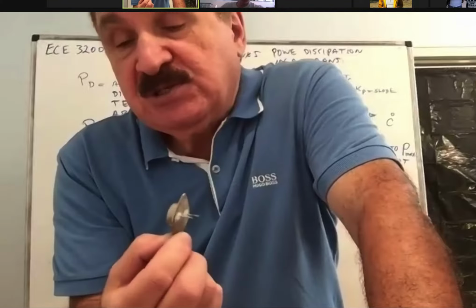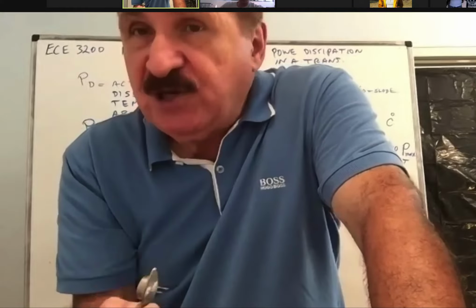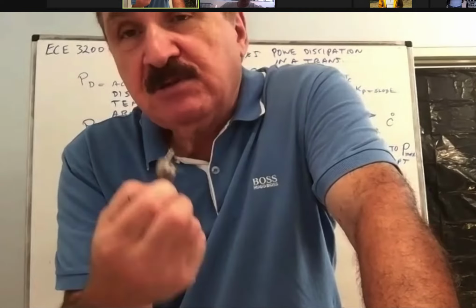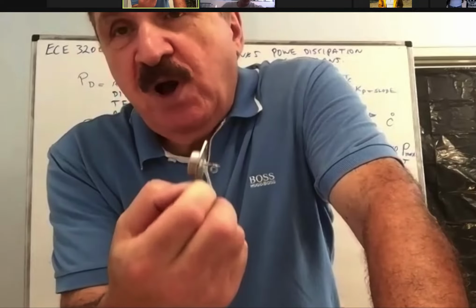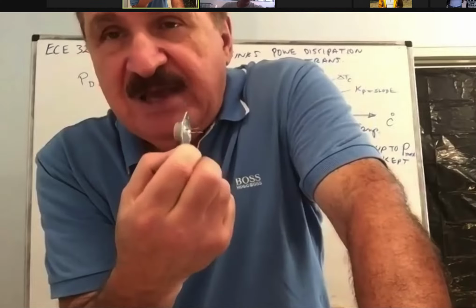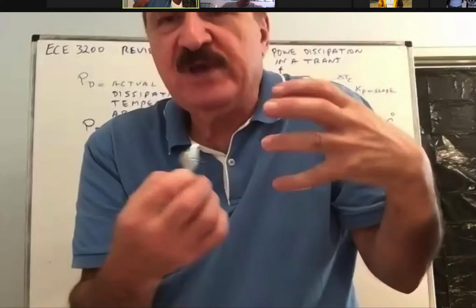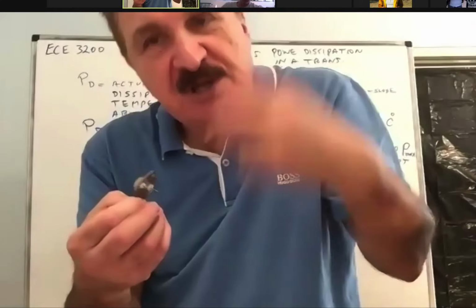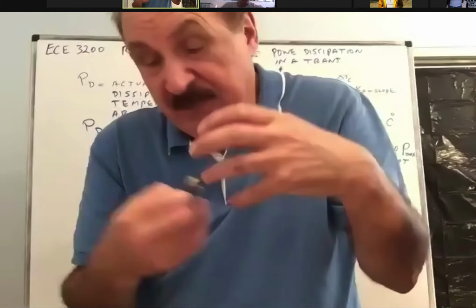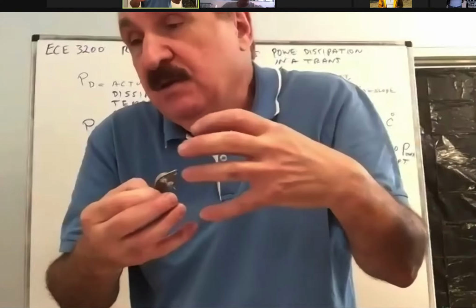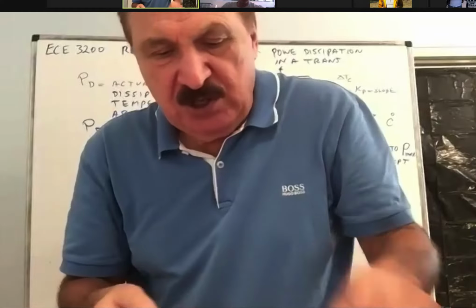But the question is, can we just put a 3-watt transistor there and hope it will function? The answer is no, not quite, because when you dissipate 3 watt in a transistor of that small size, its temperature will rise quite high, and therefore its power handling capability will decrease. Whatever the manufacturer says Pmax is, let's say, 5 watt, that Pmax is subject to a standard temperature. So here it is.